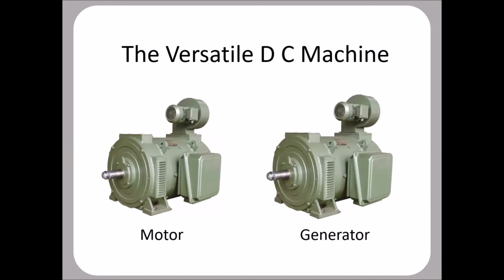Well, the perceptive amongst you will say, well, I can't see any difference between them. Well done you. There isn't. A motor can act as a generator and a generator as a motor. It's just a machine. If you ask it to produce mechanical output power at the shaft, it will draw electrical power. If you put mechanical power into it, for example, by connecting it to a diesel or a petrol engine, it will produce electricity. You don't need to change anything, rewire it or anything.